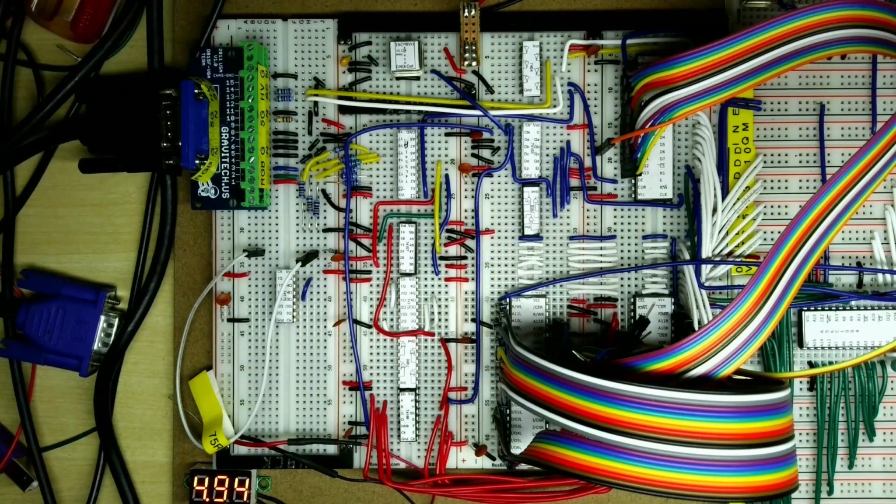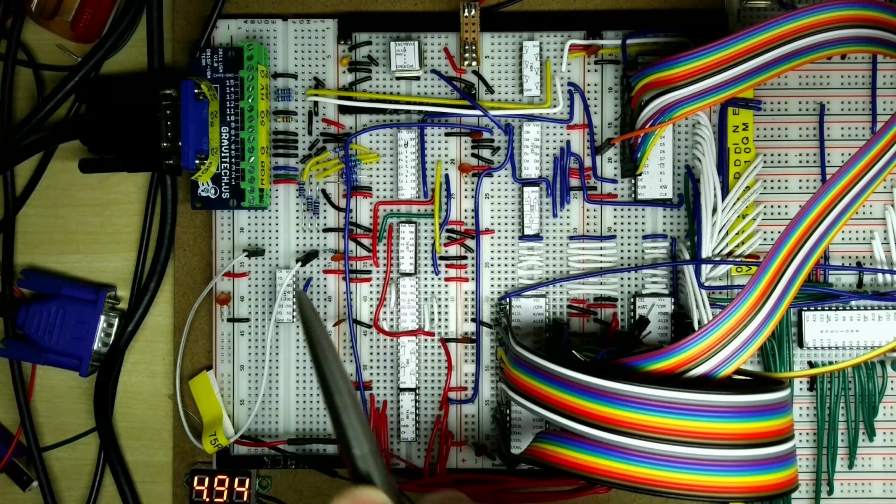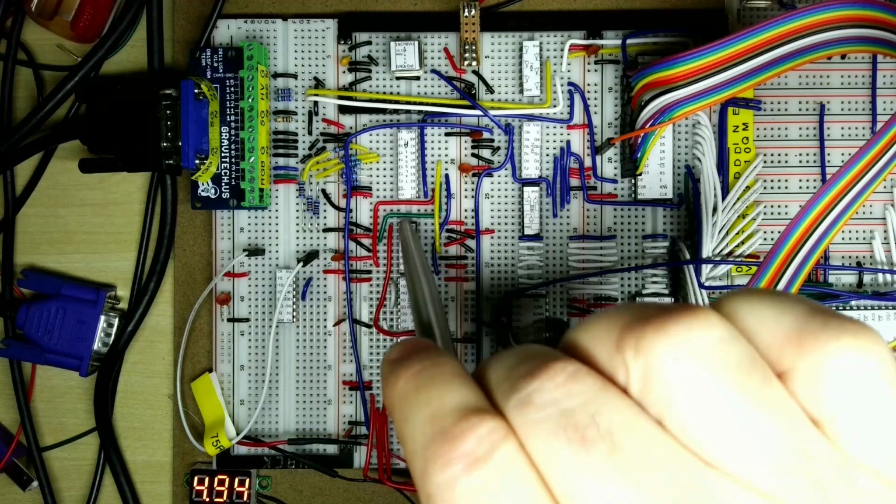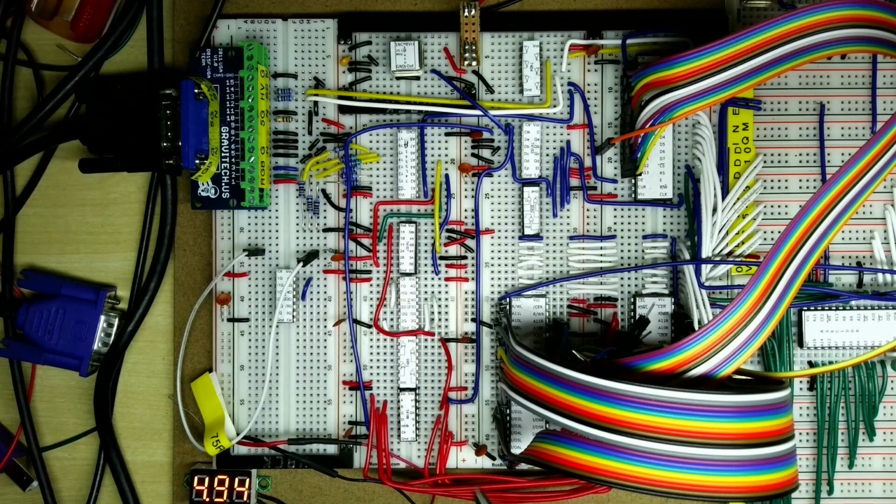And what I've also done is add an XOR gate down here, so we're only going to need one XOR gate to do this. And there's two flip-flops I've got here, which I'm going to be using for delaying some of the signals. And then this is the existing buffer as it exists already. I've modified slightly some of the routing of the wires here just to make it easy to plug in and out these new bits.